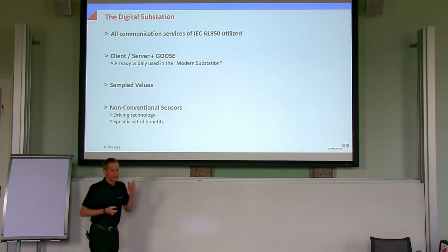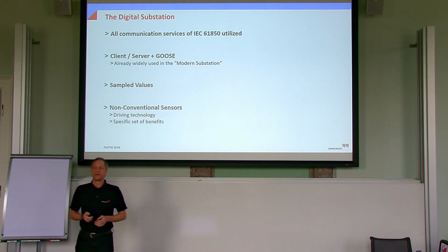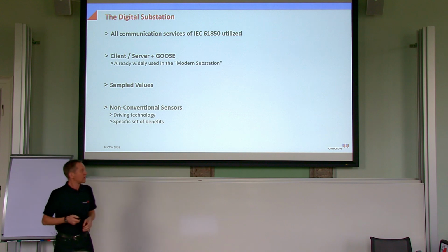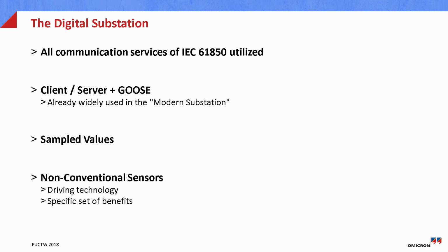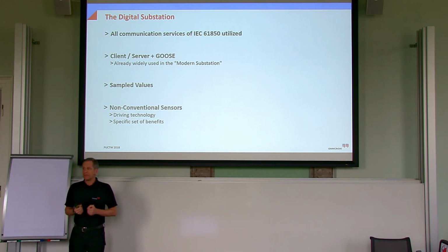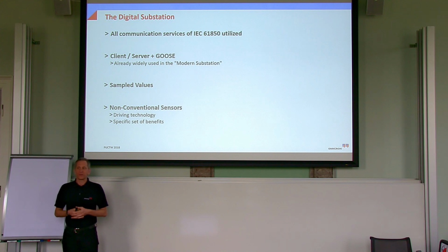Good. The digital substation uses all kinds of communication services that 61850 offers. We have already a lot of stations in place that we could call modern substations, where we utilize GOOSE and client-server for the SCADA systems. But now here, the digital substation assumes and implies that the sampled values are also applied.